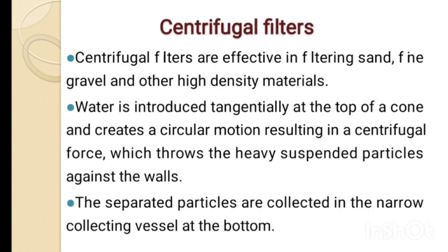Then centrifugal filters. Usually centrifugal filters are effective in filtering sand, fine gravels and other high density materials. Water is introduced at the top of the centrifugal filter tangentially. So it creates a circular motion resulting in centrifugal force, which throws the heavy suspended particles against the wall. The separated particles are collected in the narrow collecting vessels at the bottom.